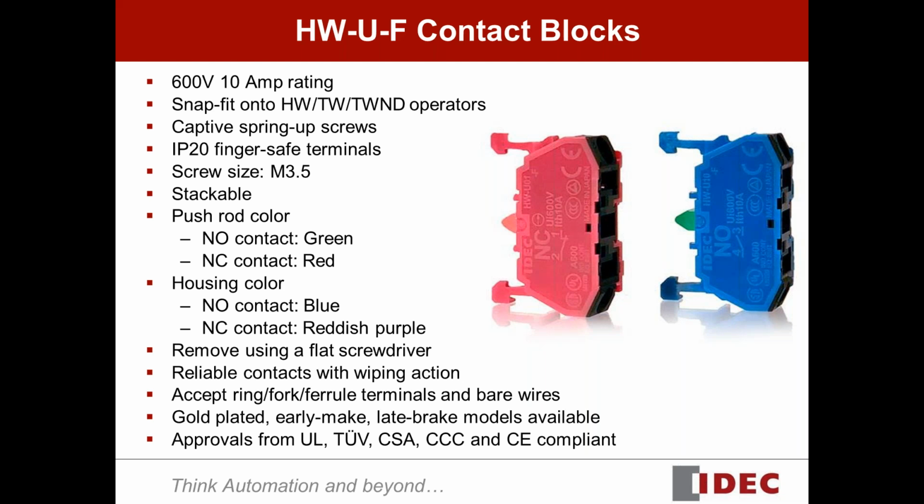They have captive spring-up screws, so you don't need to open up the screw before you do the wiring. The screws are already sprung up, so you just insert the wire and tighten it down immediately to save labor costs. They are IP20 finger-safe. The screw size is 3.5 millimeters, and they are stackable.